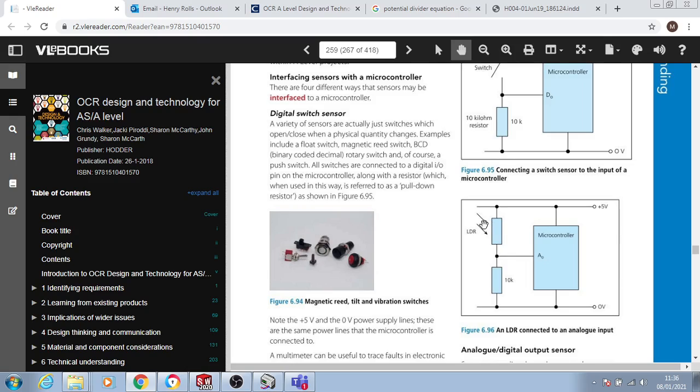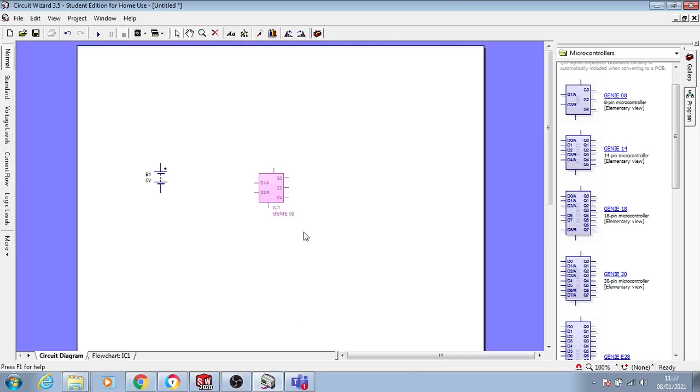If this is like 1,000 ohms and this is 2,000 ohms, then this is going to be at 2/3 of the voltage, 3 and something or other volts. Okay, and that's pretty much it. So we'll just reconstruct a circuit like that, play around with it. We'll do some questions, show you a simple formula, and that will just about cover this video.